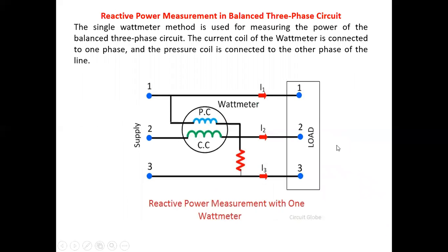The next method is measurement of reactive power in a three-phase balanced circuit by using the single wattmeter method. In that system, the reactive power can be measured by using a single wattmeter. For the measurement of reactive power, we take a load that is inductive or capacitive, which contains reactive power.